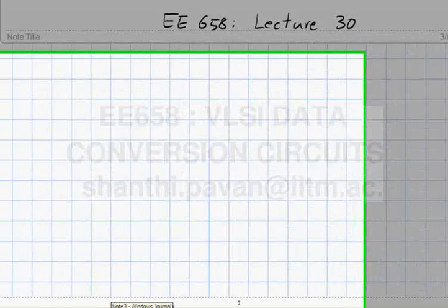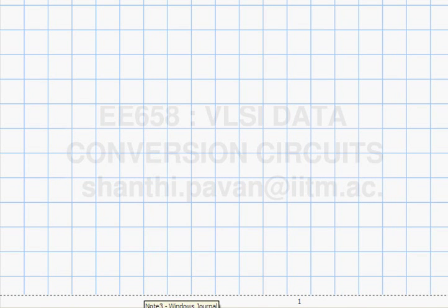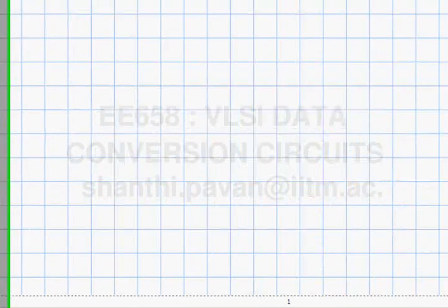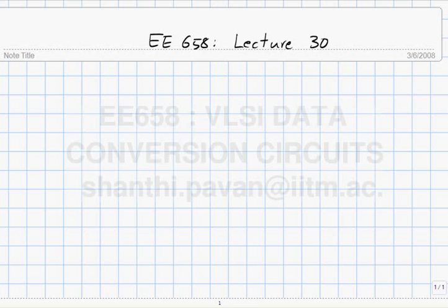So far in this course we have looked at A to D conversion. Apart from studying the basics and how you define various specs, we have seen a simple way of doing A to D conversion, namely the flash analog to digital conversion technique, where the idea is basically that of a dumb search. You divide the input into a bunch of bins and figure out in which of these bins the input lies by exploiting parallelism. You put many guys on the job at the same time.